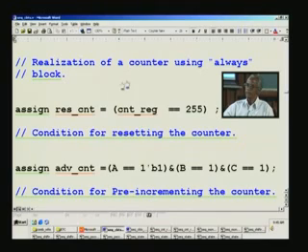And if it is ASIC, I have tried 0.13 micron technology also. I have done it for MPEG video compression, say DCTQ, etc., which I will be showing later on in the design applications. In that I had achieved around 270 megahertz in 0.13 micron technology. You can jack it up to 300 megahertz. The only thing is, synthesis will take a long time in ASIC.